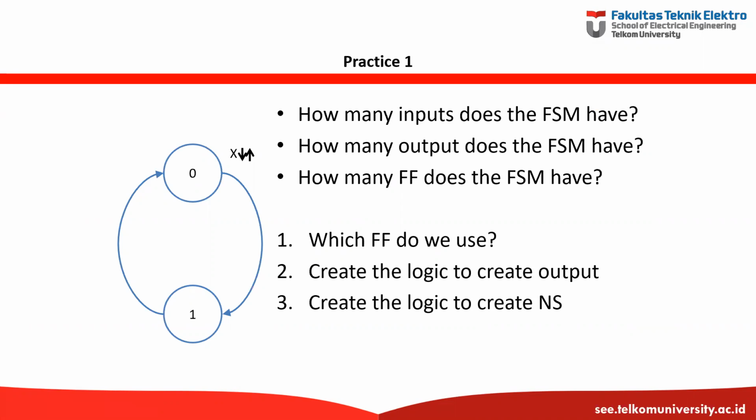Just like last week, there are two parts of how to design the sequential machine. The first one is starting from the case study, a story. From the story, you can create the state diagram, and then from the state diagram, you can create the FSM. From last week and also part of this week, we're going to discuss how to design the FSM starting from the state diagram. So we are given a state diagram, and we are supposed to design the finite state machine.